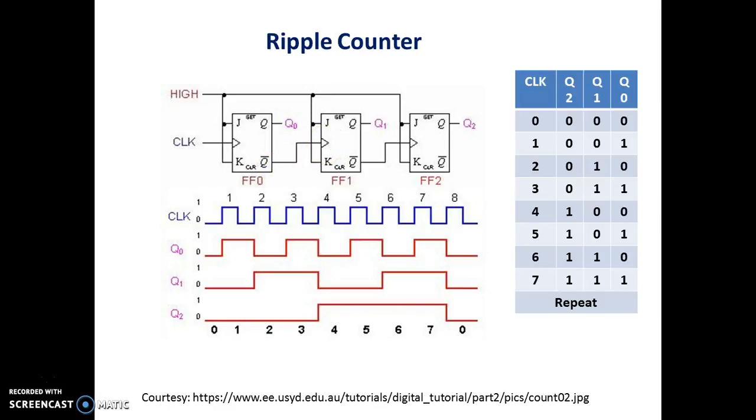So when the clock changes from 0 to 1, as it is a positive edge trigger flip-flop, that time the Q1 changes. So we can see the change here, 0 0, then 0. It will take 2 stages, 0 1 0 1. So it would be changing after 2 clock stages, and this is how we get the transition.